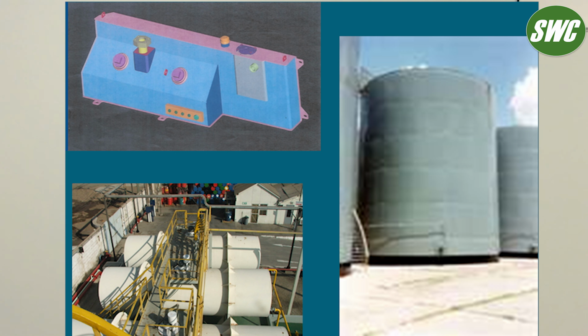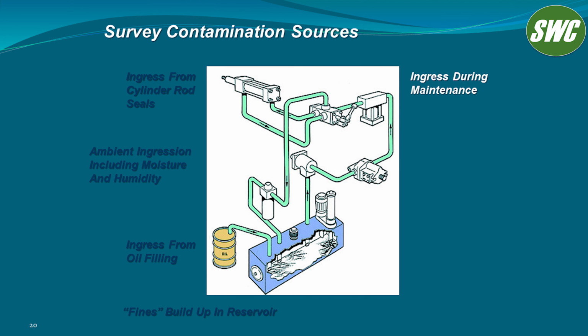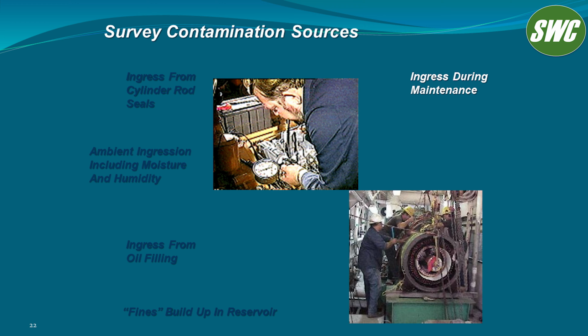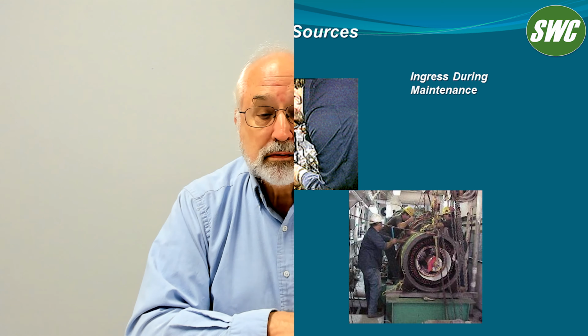Modern mobile equipment compact reservoir designs are an issue for consideration, as well as large storage tanks, all of which can accommodate elusive fines. When conducting maintenance, make sure you have as clean an environment as possible. Your ability to police contamination is going to be very related to how clean that environment is. New oil is not necessarily clean oil, and new components are not necessarily clean components.